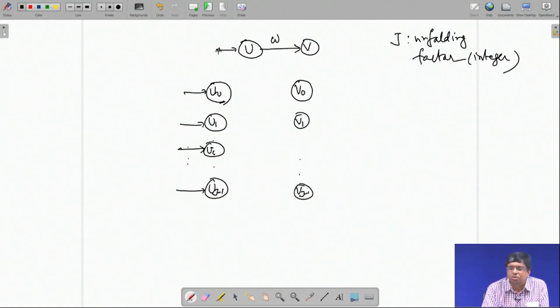And then in terms of that clock, I have got w number of delay here. But now when you parallelize, system is slower, input is faster. So system clock is slower, system clock period is j times the original input clock, or speed is j times less. So in terms of this system clock, because they are working at a system clock, how many number of delays per edge between U type to V type processors? To answer this question, I will come back to the timing diagram.